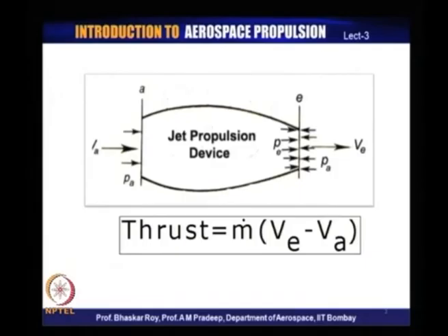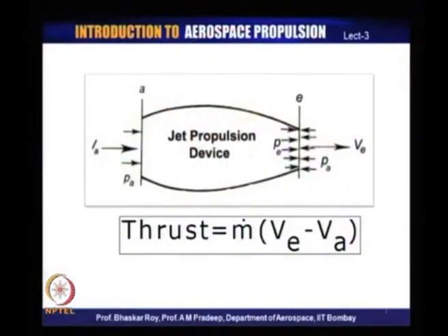As shown in this picture, the incoming velocity and the outgoing velocity are exactly in the same line, and as a result the action of the exhaust velocity and the reaction produces a thrust in the same line in which the velocities have come in and gone out, that is, in the line of action of the exhaust velocity, or exhaust jet more specifically.